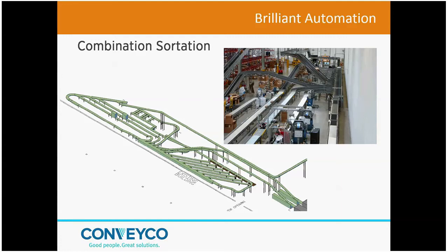The packing needed dunnage, it needed some paperwork, it needed to be sealed, and then it needed to be shipped. A combination sorter, if your net rate is 20 a minute, this sorter was designed for 40 to 50 a minute so that every carton can go through twice.